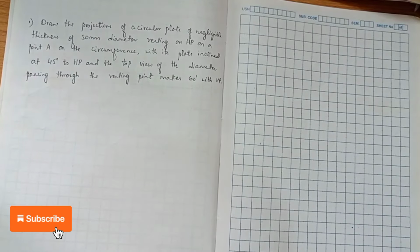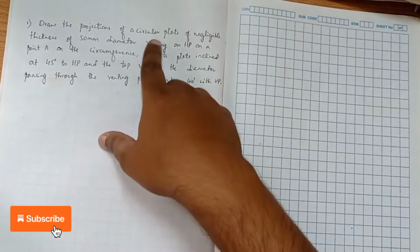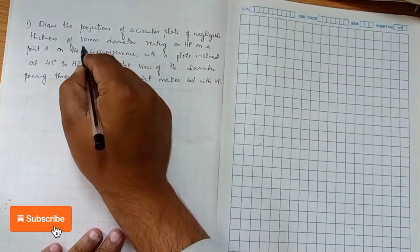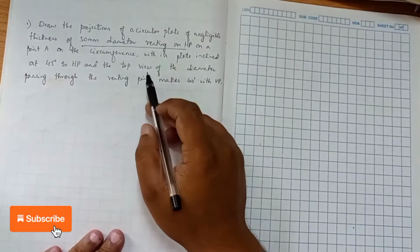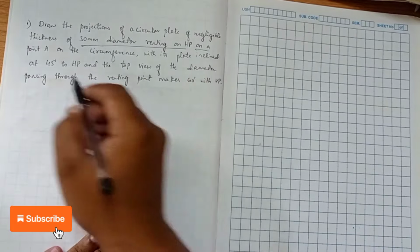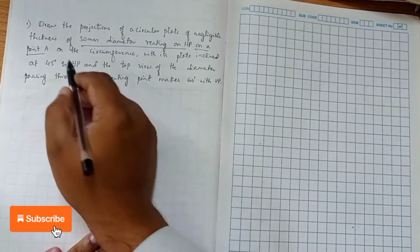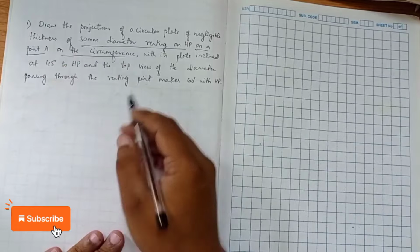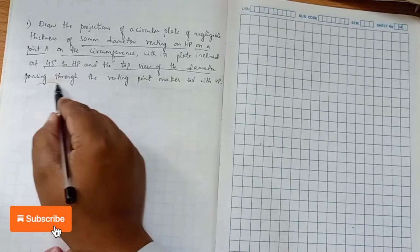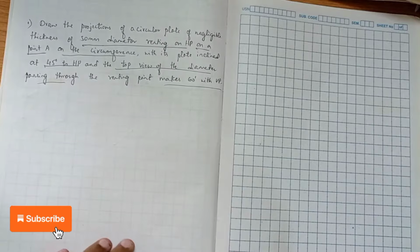Today we are going to start a problem on circular lamina. Okay, so draw the projections of a circular plate of negligible thickness 50 diameter resting on HP. So you can see that. So we have to construct a circle of diameter 50 resting on HP on a point A. That means we need to consider a starting point A here on the left hand side. So on the circumference we have to consider a point. So with its plate inclined at 45 degree to HP and the top view of the diameter passing through the resting point makes 60 degree to VP. So it is one of the normal type of problem.